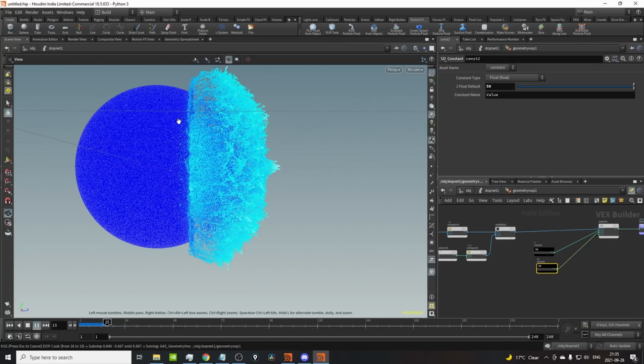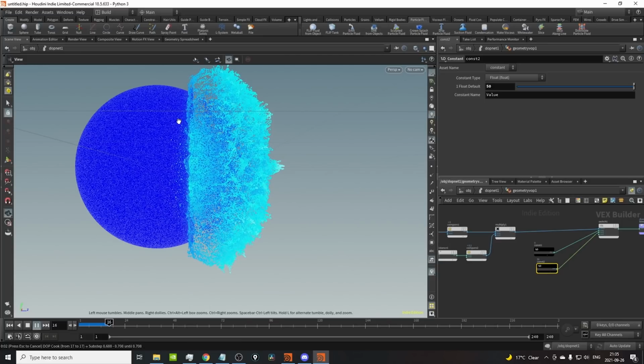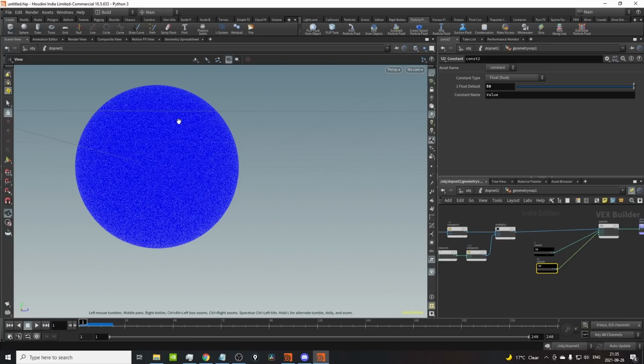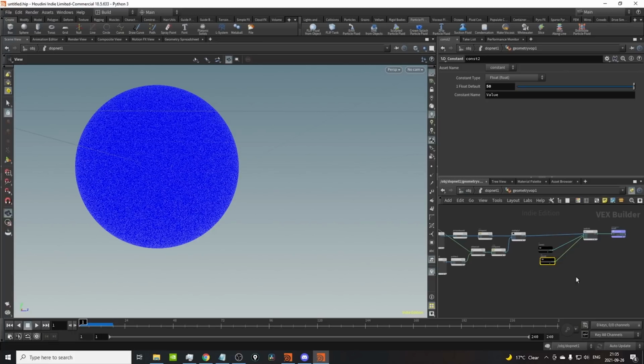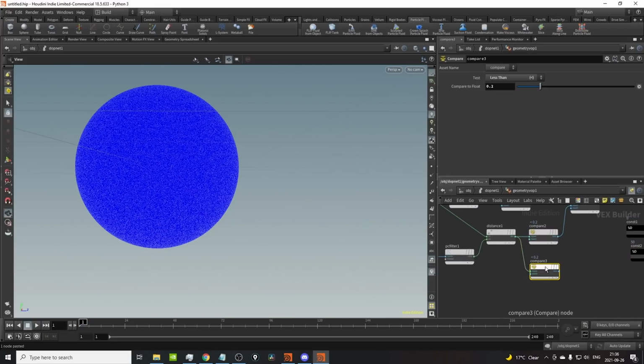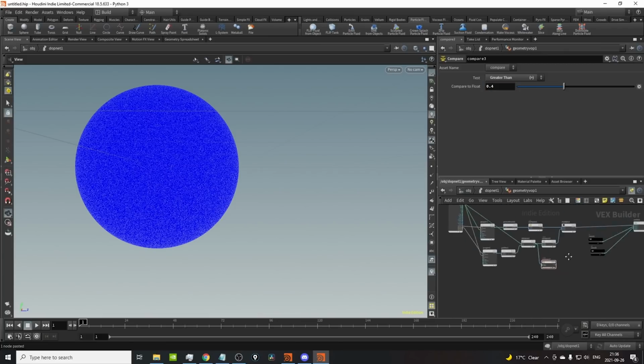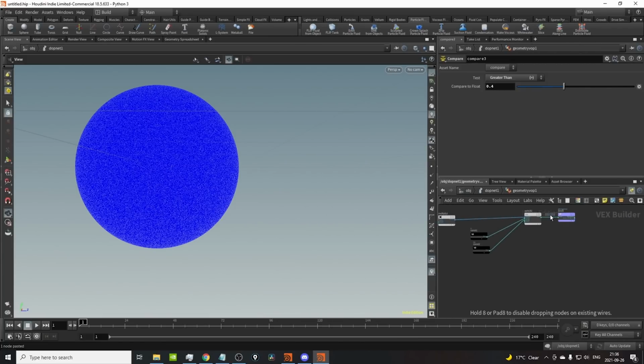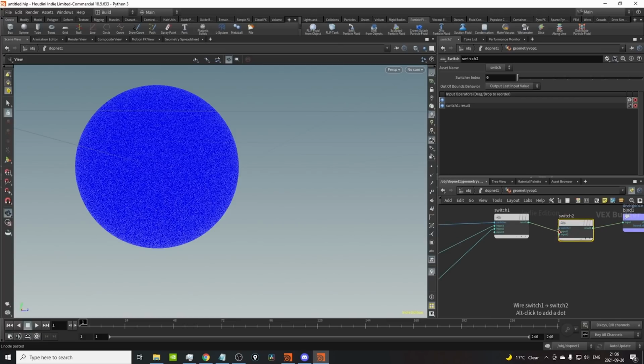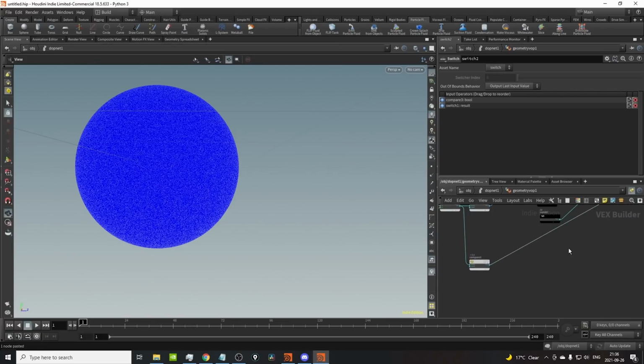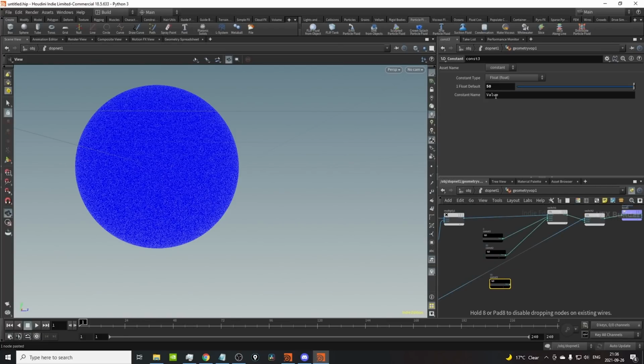And this could be even more interesting, right? Because we're just setting that divergence on every single frame. We can go even more extreme and say, well, we want to introduce the positive divergence within the shell, when it's in this area around the sphere. But what happens if we're greater than our distance lookup? And let's add a little bit more to it. Maybe we want to switch from whatever we're adding divergence-wise here and instead go to a negative divergence, right?